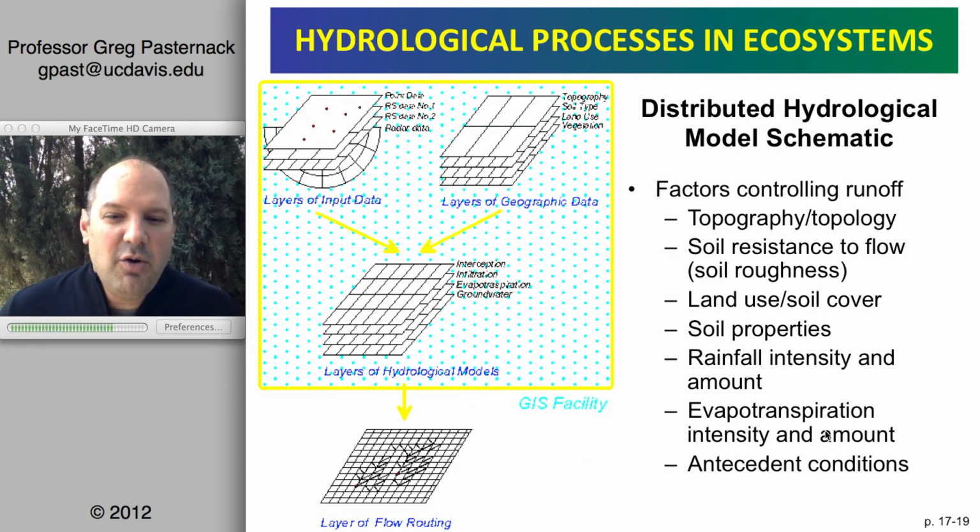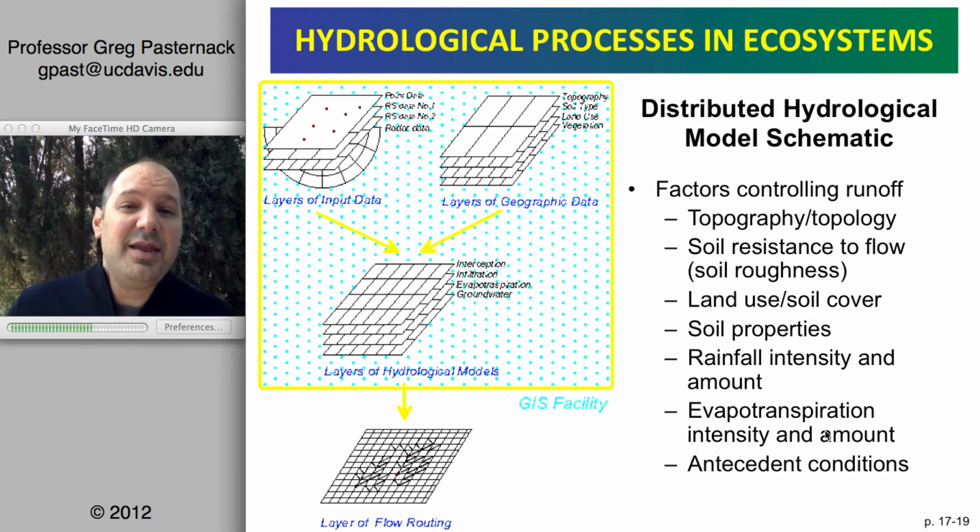Okay. So now let's take a step back because we've been really far in the weeds. We've addressed getting a digital terrain model, taking the digital terrain model and determining where it's wet and where it's dry, if you were to have overland flow, determining what direction that flow would go for every cell, and then finally, whether you have enough contributing area to generate a channel or not. And that's the simplest approach for that. We're not going to get into details beyond that.